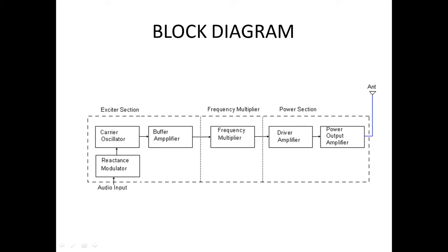Since this AF modulating signal has uneven power, it is fed into a network called the pre-emphasis network, where all the frequencies in the modulating signal are made to have equal powers. The output of the pre-emphasis network is then amplified and sent to phase modulation. The modulated output is then power amplified using a power amplifier and fed into a transmitting antenna for transmission. Now we will discuss these three sections in detail.